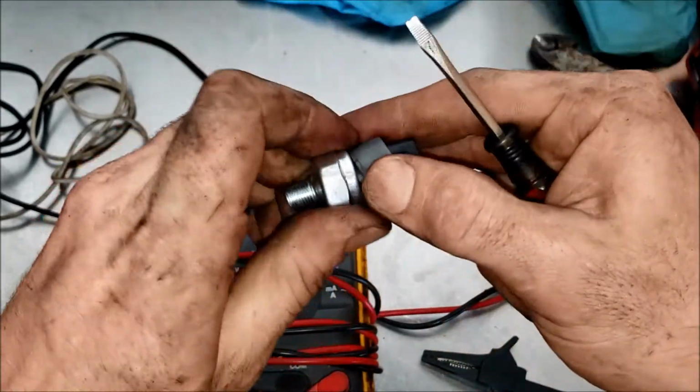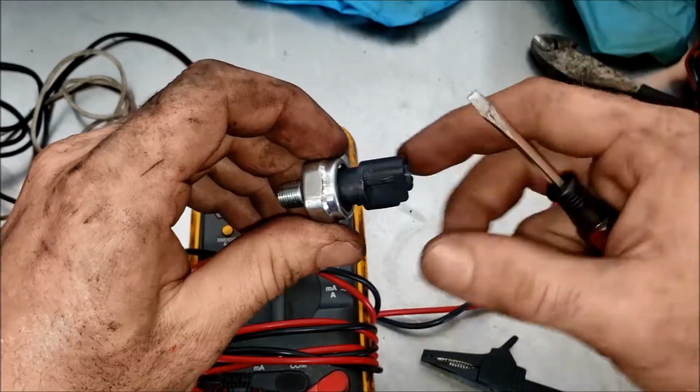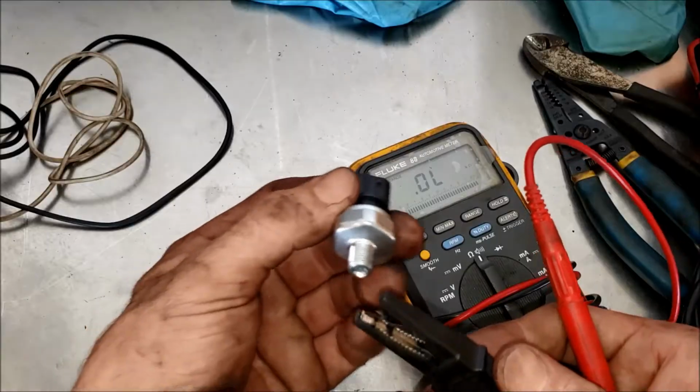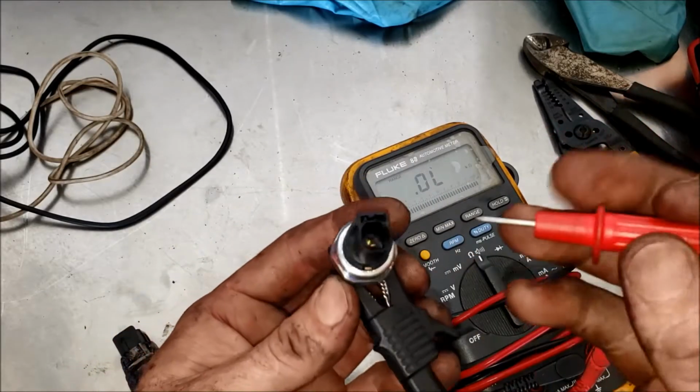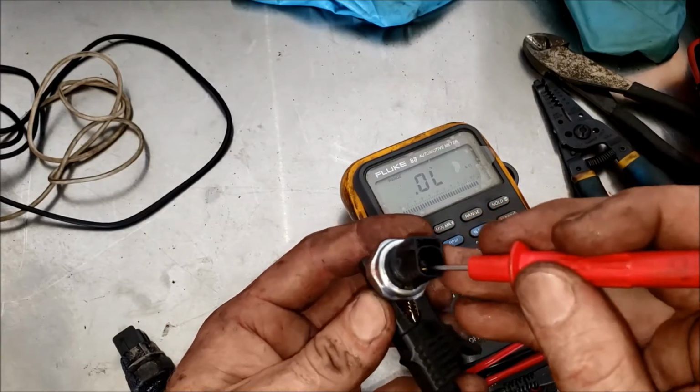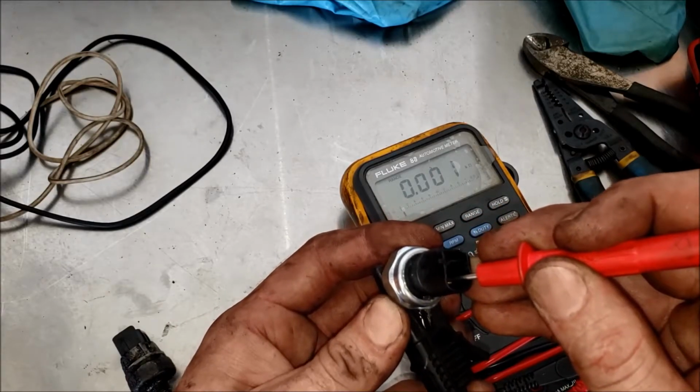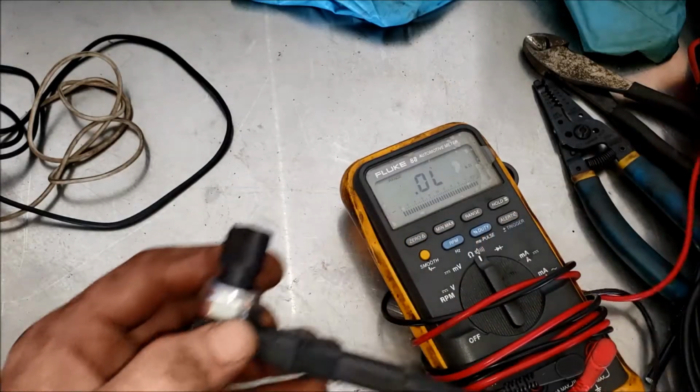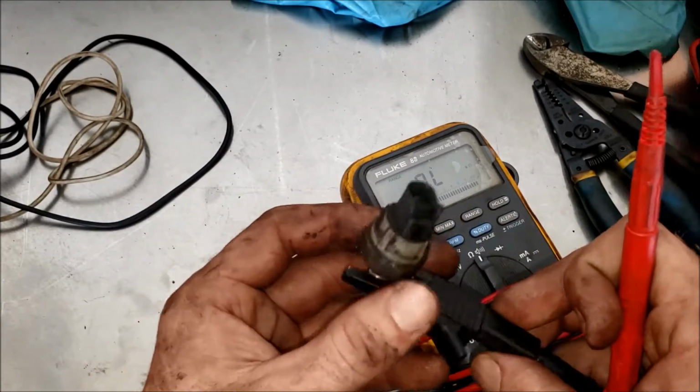Hopefully, yeah, it just slides right off there. And then I'll put that back on once we put it on. And then let's alligator clamp this to check the resistance between ground and this pin. And we've got, boom, there you go, 0 resistance. Just about anyway. And we'll see what the old one is too.